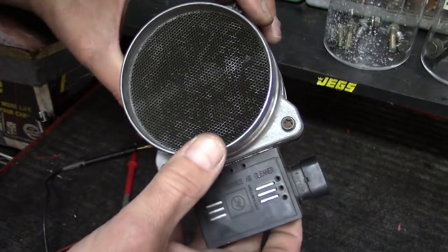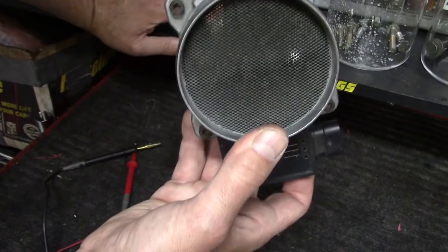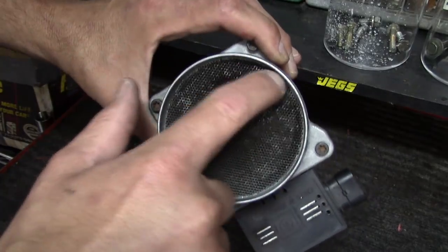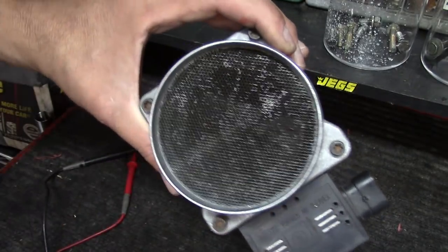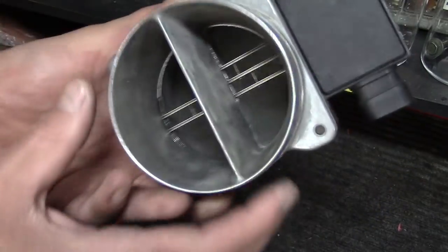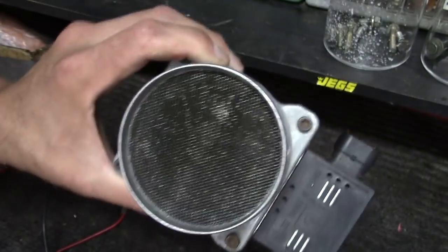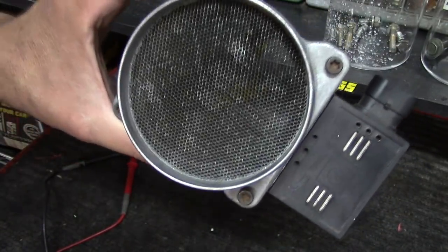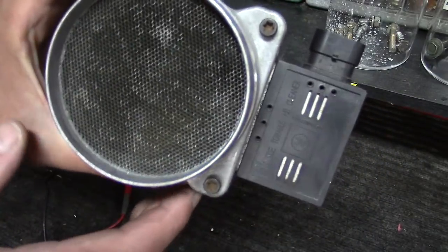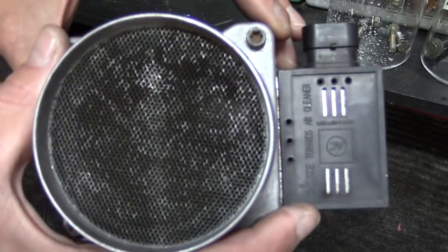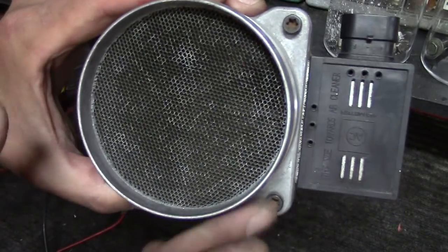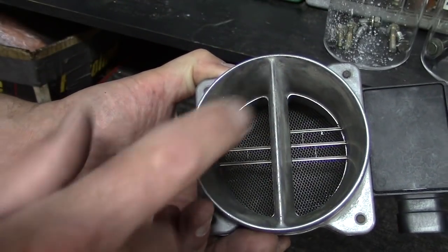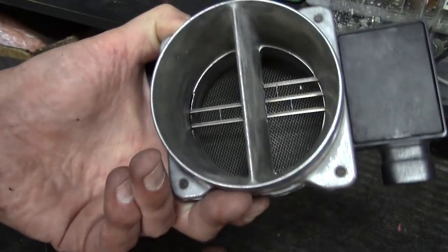of this screen. What I'm getting at is the modification that a lot of boneheads would do, and I'm talking thousands of people, where the idea is to remove this mass airflow screen, thinking that the screen is to protect the delicate wires. That is not the purpose of it. If you think about it for just a second, the air filter would do a million times better job than this screen would of that particular application. So the purpose of the screen is actually to even out the airflow so that there is an even sampling from the mass airflow sensors for the airflow coming in.